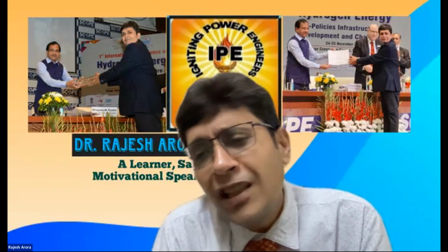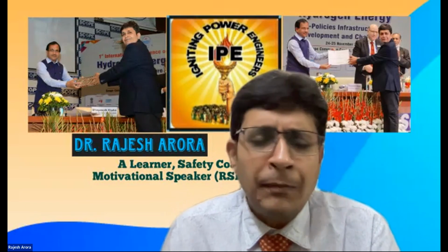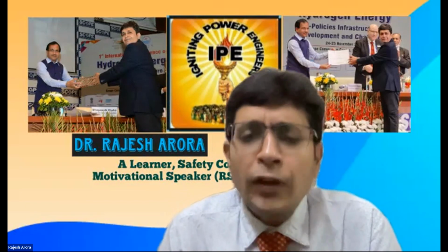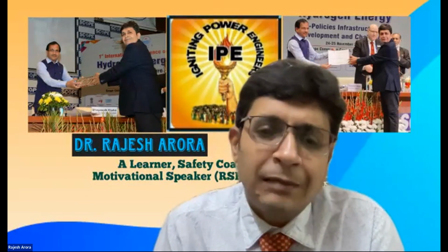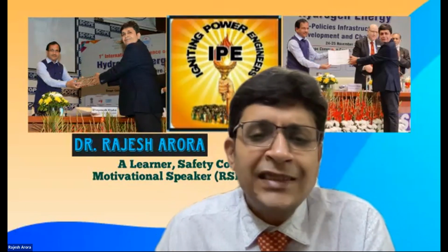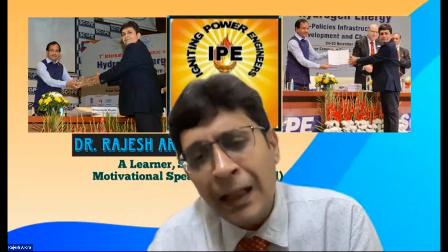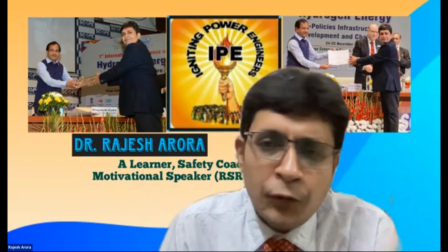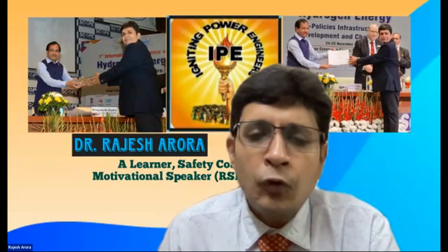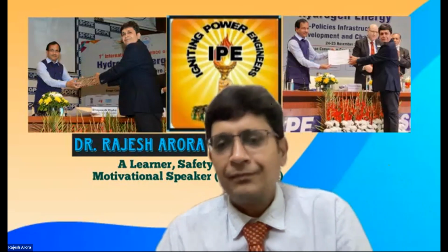Sir, actually now the scenario has totally changed. With the coming of the private distribution companies, they have come out with very new technology relays even at the 11 kV system that you are also using in your system, and those numerical relays may have all the data of the fault current that flowed at that particular time, and that data can be given. Yes, when you are using the electromechanical relay, that is not possible, I do agree, but we have to work in the direction where we can utilize the technology we have.